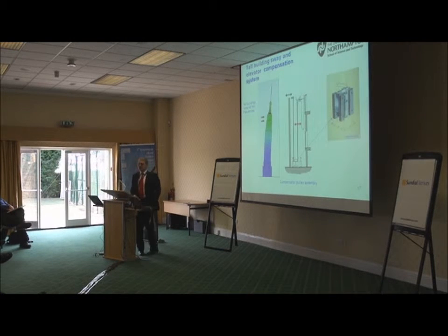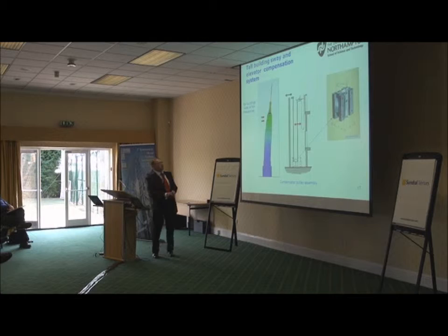Okay, now in this case study, I will take one type of behavior of the building and lift systems in terms of their dynamics. Tall buildings sway at low frequencies. When they sway, they transfer motion to the lift system, typically the car or counterweight, and the system is being excited and starts to vibrate.